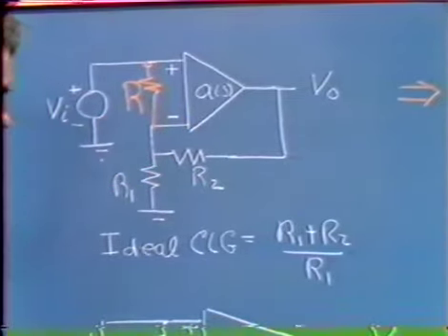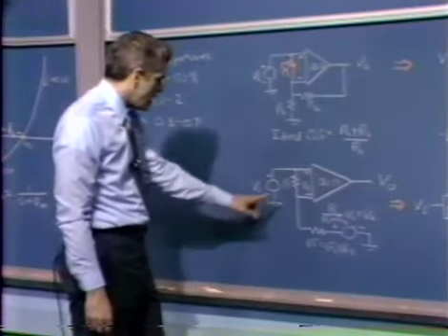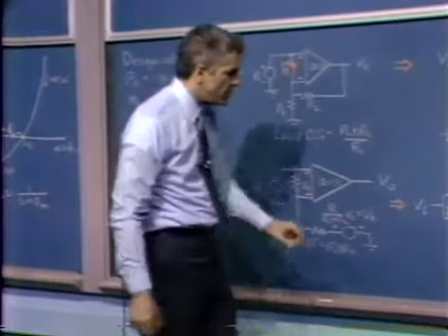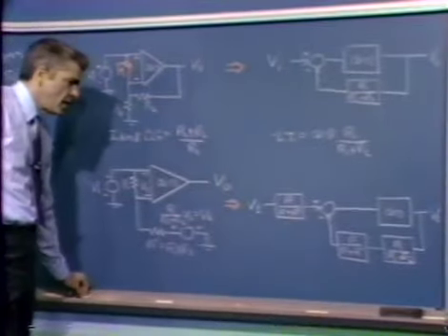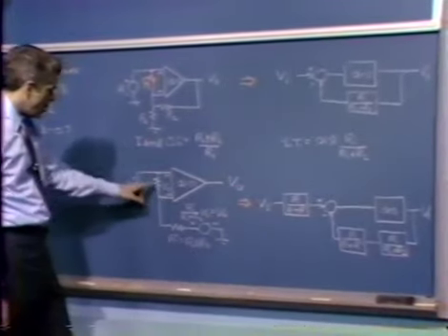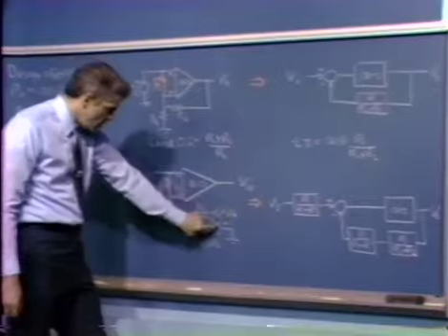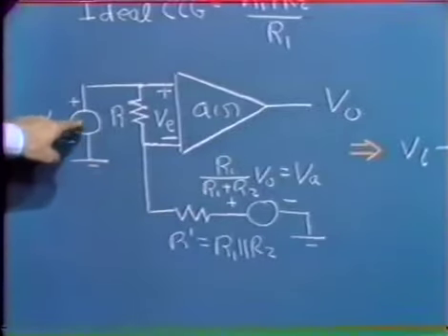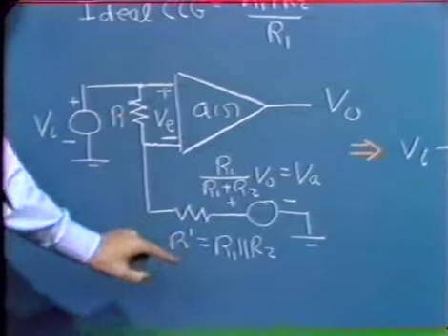Once we do that, we can get our block diagram quite directly. What we find out is that this voltage, VE, which is the voltage we're sort of trying to generate at this point in the block diagram, we can consider the superposition of two parts. We get the contribution that exists when this generator is 0, but VI is present. That's simply VI times R over R plus R prime.